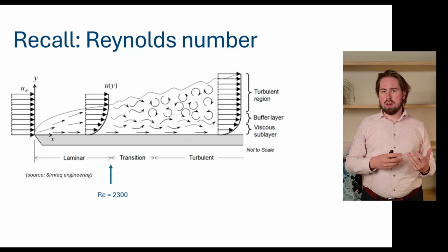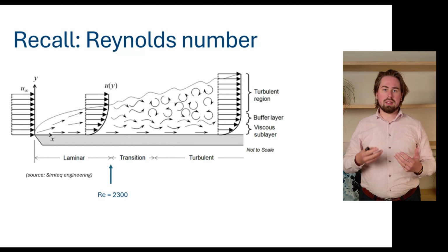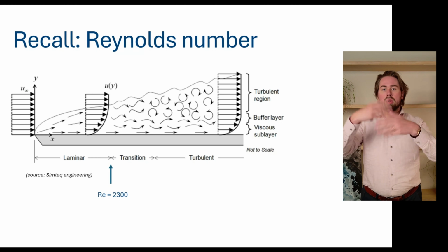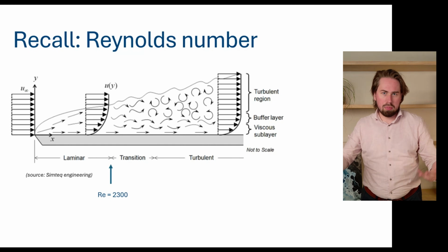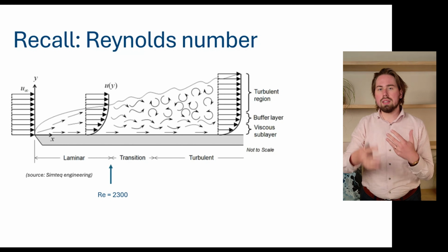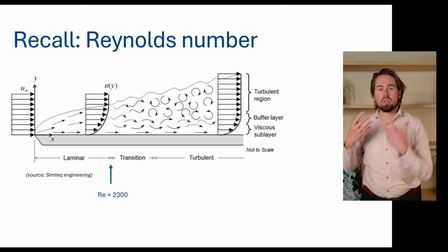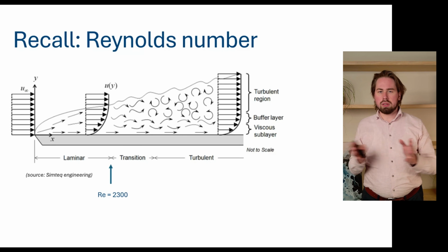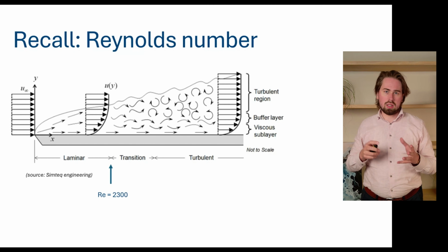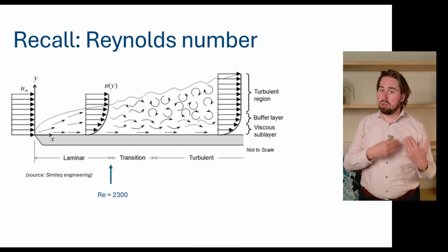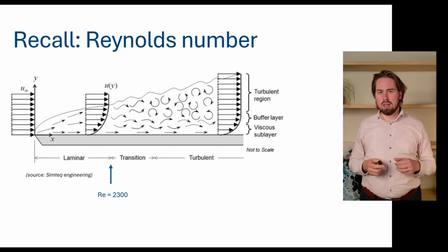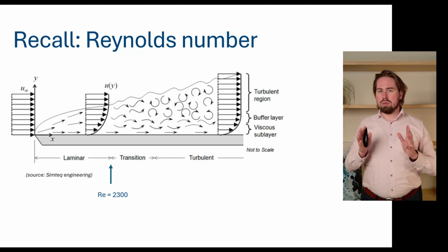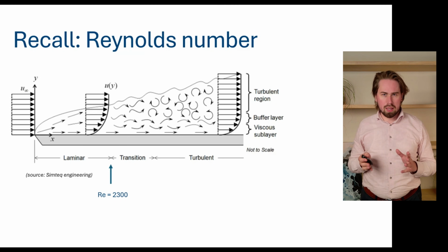Whereas if you have a higher flow rate and your droplets are rushing through the pipe, they tumble over each other, and once in a while every droplet would touch the wall, and it's easier to transfer heat in that way. And that's a turbulent flow range. And between the laminar and the turbulent flow range, there is this transition zone in which the fluid is neither 100% laminar nor 100% turbulent. And the onset of this transient zone is typically around 2300 for smooth pipes.